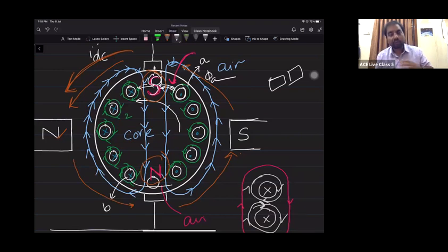So here also, the armature rotates because of a continuous attraction and repulsion, so how many magnetic fields are required? Two magnetic fields are required. The next question is why the relative speed between the two magnetic fields should be zero. If I want a continuous torque, I need a continuous attraction and repulsion. Further, the relative speed should be zero, and hence the poles should remain stationary with respect to each other. Is this point clear? Confirm me.